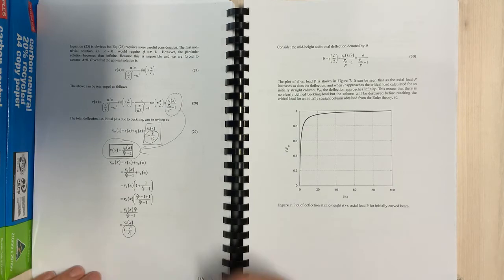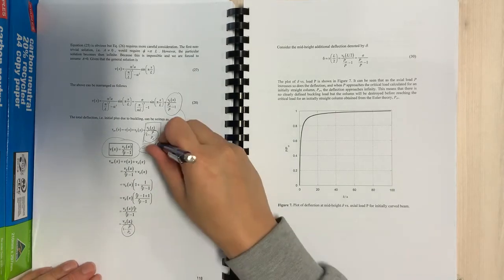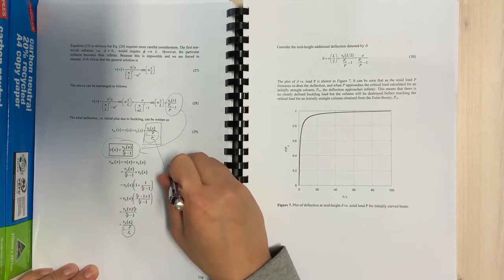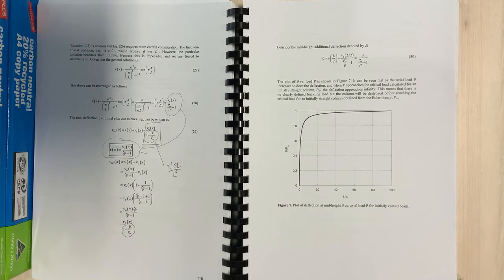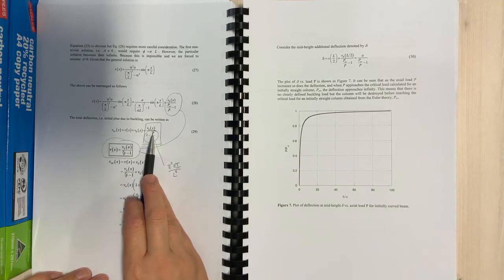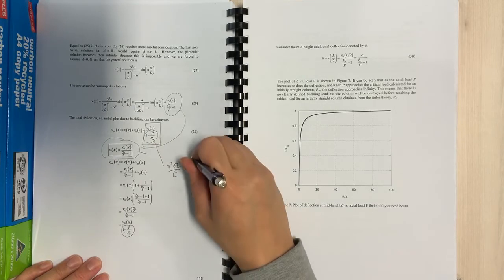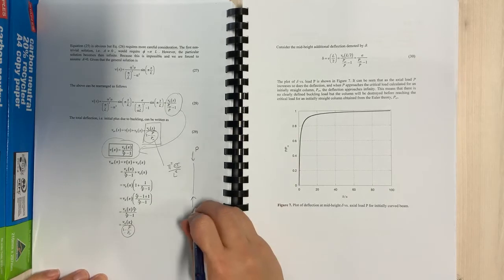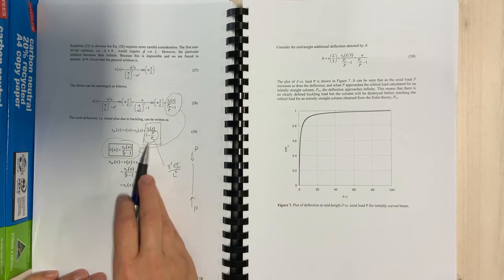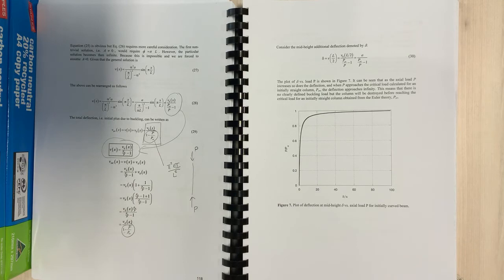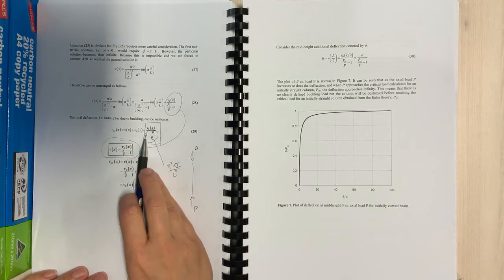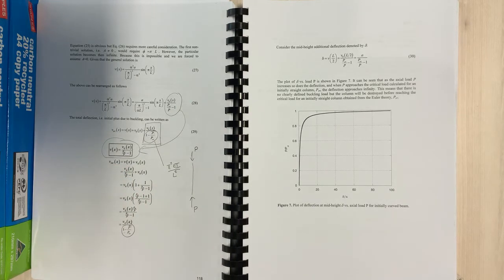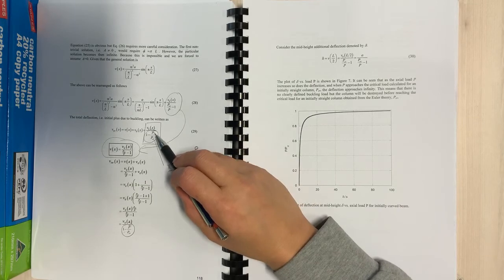So in this equation, P is the load that's being applied. PCR is of course pi squared EI over L squared. So we can see that when the axial force P that's been applied is equal to PCR, you've got 1 minus 1, and then your deflection goes to infinity, because anything divided by 0 is infinity.